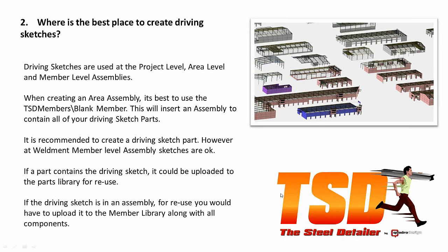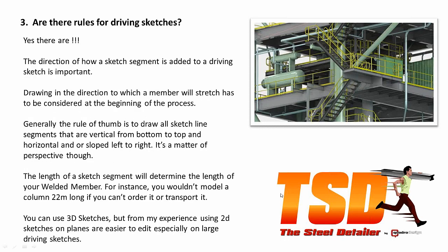Now, the rules for driving sketches. Yes, there's certainly some rules that you have to follow. Now, the direction of the sketch segment that you put in a sketch is really important, because that's the direction in which, when you attach your welded member or your section to it, it's going to stretch.